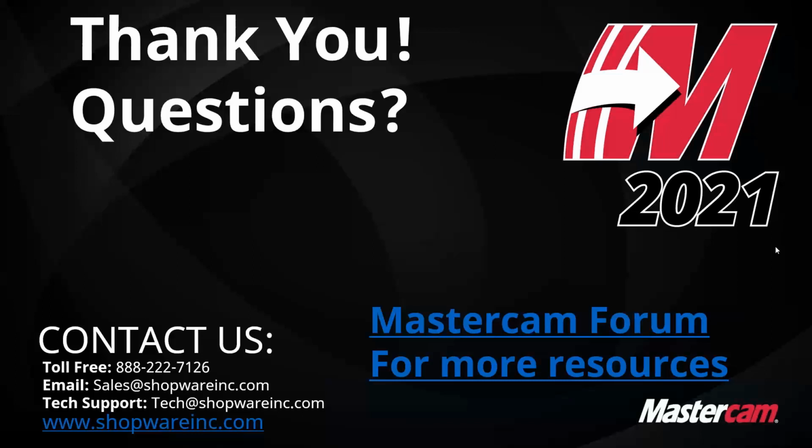I got some ideas based on a lot of questions we had today about different graphics cards and graphics settings in Mastercam and graphics card level settings. Like I responded to the whole audience there where Brian had a question about his K220 graphics card. You might get that warning, like I said in my answer there, that your graphics card isn't CL 1.2 compatible. Don't worry about that too much. Mastercam will still work fine.